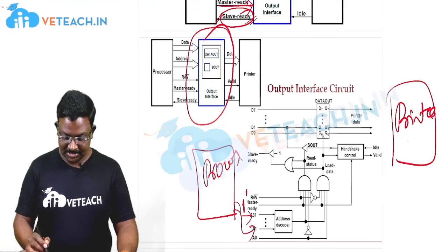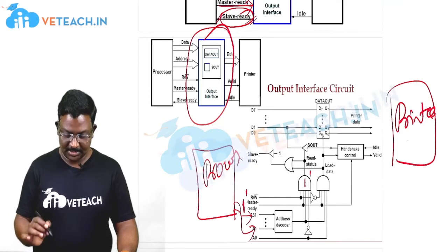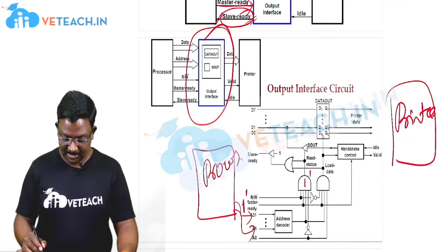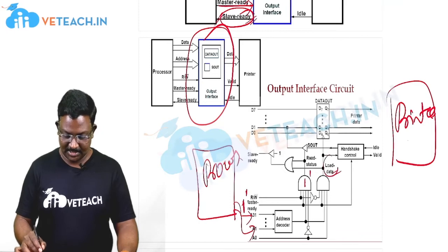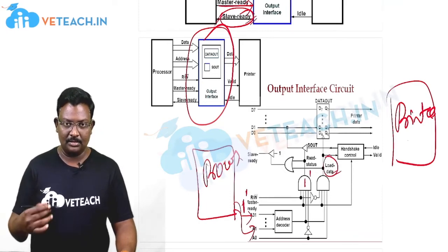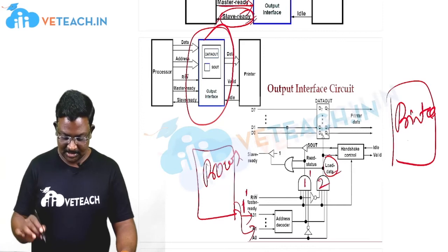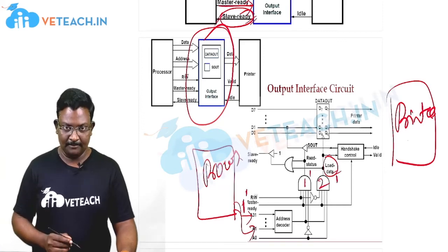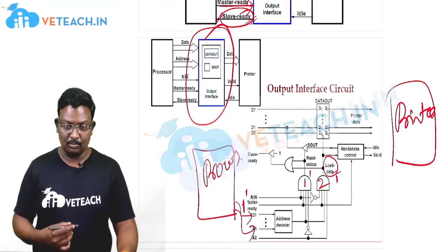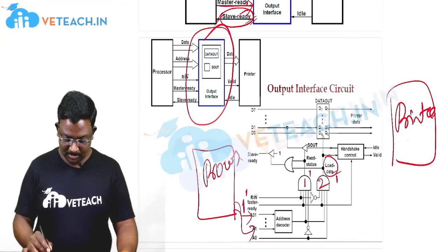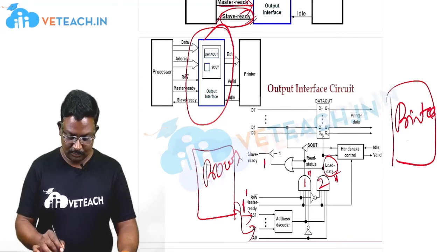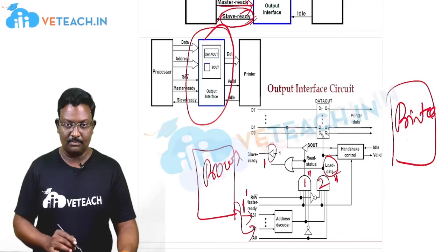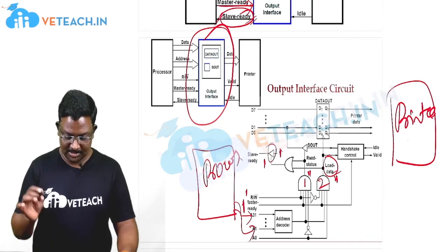The read status is going to be 1 whenever the output of this AND gate is equal to 1. Similarly, the load data here, which in the previous presentation we represented as read data, but here we are loading the data to the output device. For the second AND gate also, the output will be 1 whenever the output device is ready. Depending upon these two gates' outputs we place slave ready to 1, and here also the tri-state buffer input is continuously given as 1.